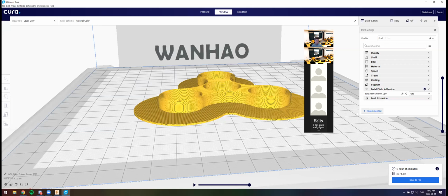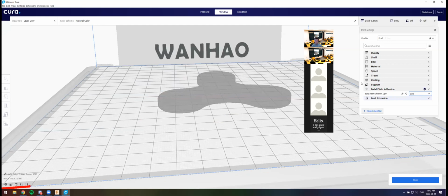So Laszlo, again, you can use any one of these for your heated bed. It's just going to depend on the situation. If you're printing something really tall, like a rocket that has a small area at the bottom, use a brim. If you're printing something with a big surface area and you don't think it's going to unstick by itself, you can use a skirt. If you really need a flat bottom for your object, use a raft. And I wouldn't suggest using none, because skirt is always just a good way to get flow going.